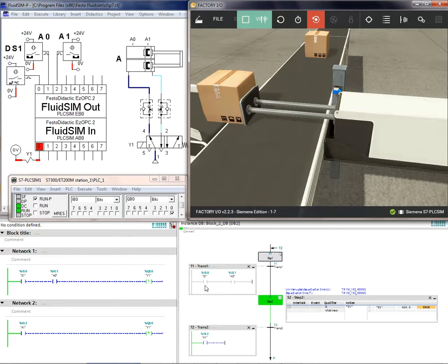In the graph set language, when these conditions turn on, the program goes to the next step, as you can see. This is the next step, and this step commands Y1. This is a momentary command, Y1 or Q0.0, true means on. This is true, means on. Okay, let's see what will happen in the next step.